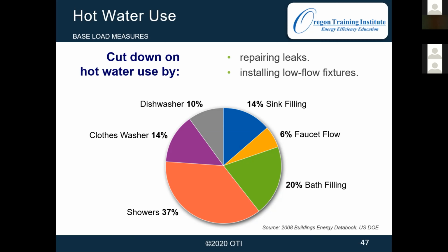And the faucet aerators, I think they're only going to test you on it on the QCI exam, but just in case, the replacements need to meet the federal limits on faucet aerators, which are pretty lax, or not very conservative. I believe it's 2.5 gallons per minute on the shower and 1.5 on the faucets. And that's the federal limit. We can go lower, but if we're replacing them, then we can't go higher than those.